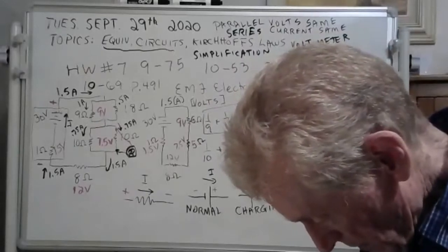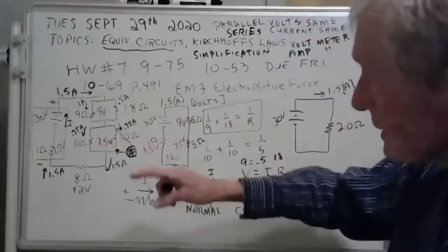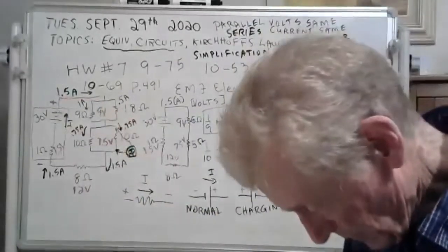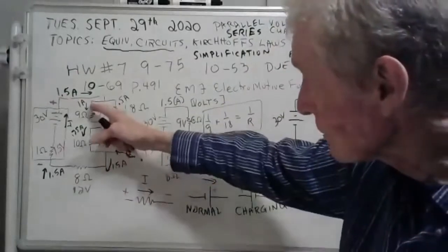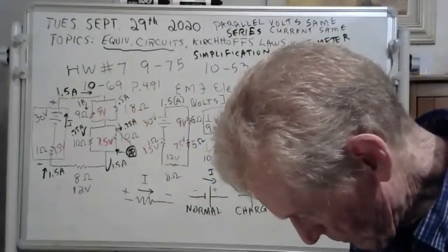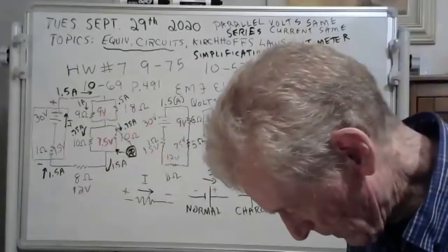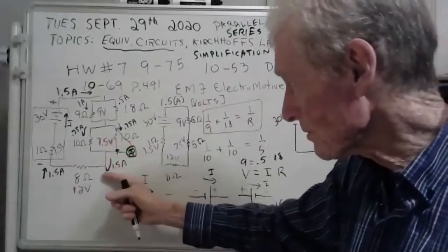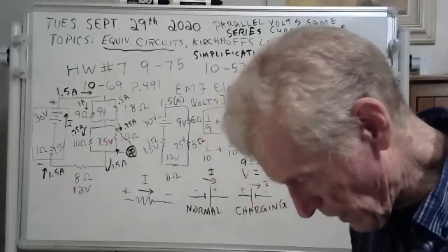They said one of the currents is 1.5 amps and another current is 1 amp. Well, we got that. Yeah, there's 1.5 amps. And they said that was one of the currents. Then they said there's a 1 amp and a 1/2 amp. Look at here, it splits a 1 amp, a 1/2 amp. That's exactly what the answer book says. And then they said there's 0.75 amps and 0.75 amps. Hey, that's us. We got that right. And then they said something about 1.5 amps. Well, I think that's just coming out of here. You go back to 1.5 amps. So we got everything they got, but then they go on and do the powers.